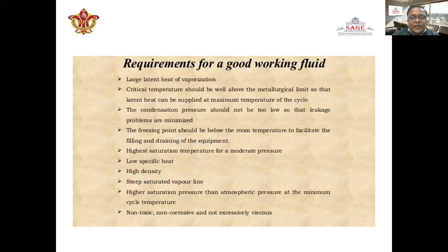Requirements for a good working fluid: a large latent heat of vaporization. The critical temperature should be well above the metallurgical limit so that the latent heat can be supplied at the maximum temperature. The condensation pressure should not be too low. The freezing point should be below room temperature. Highest saturation temperature, low specific heat, high density, steep saturated vapor line, higher saturation pressure than atmospheric pressure, non-toxic, non-corrosive, and not excessively viscous.